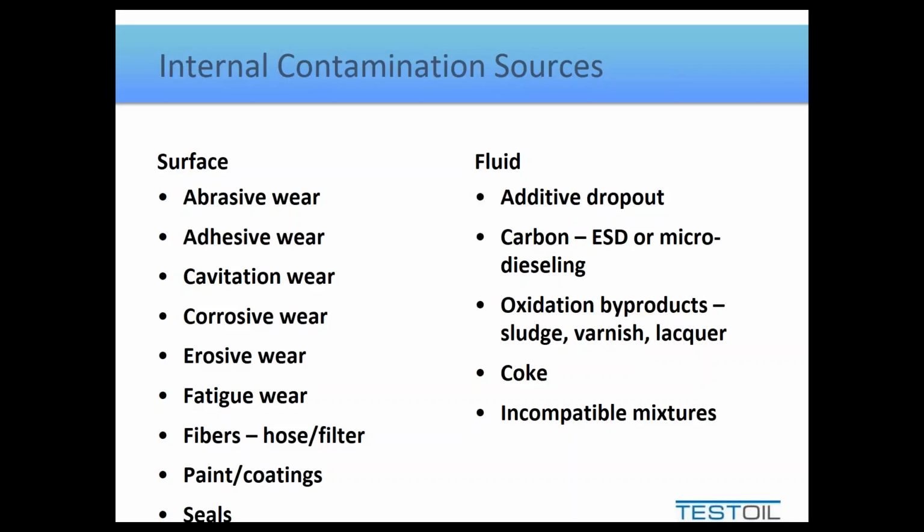Some of the other hardware that we use as part of our lubrication system has the ability to contribute particulate. Certainly any hoses that we have may, as they wear or degrade over time, release small rubber or whatever other materials they are made with particles, as well as the fibers that are holding it all together. Filters, though they're designed to remove things from oil, sometimes contribute if they begin to fail. Paints and coatings don't often wear, as they're not typically used in high turbulence areas, but they can degrade over time, particularly if we don't have a suitable lubricant in there. If we've got something incompatible, you will dissolve or otherwise alter the coating that may be protecting the metals, and as the paint wears off, it becomes a contaminant.